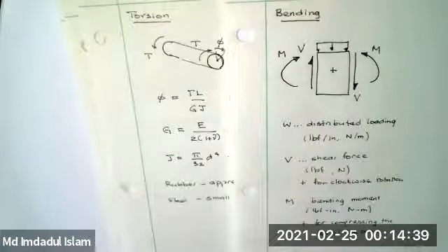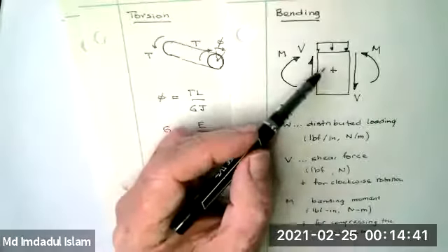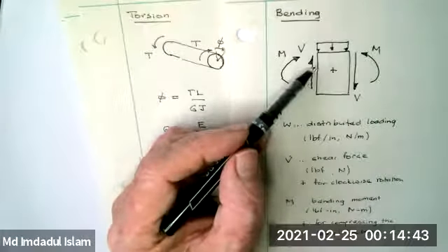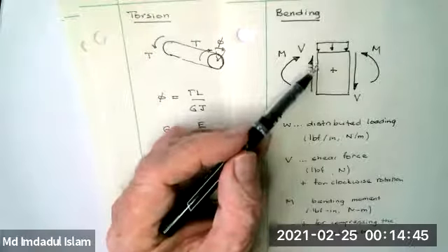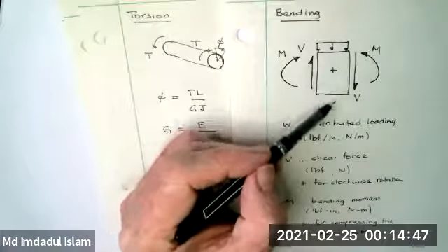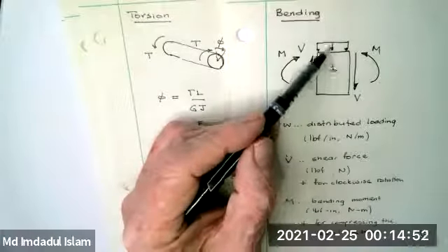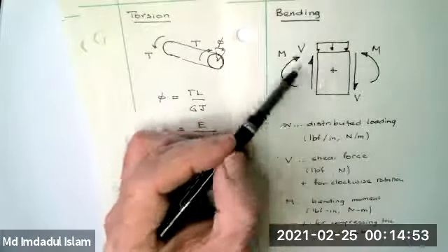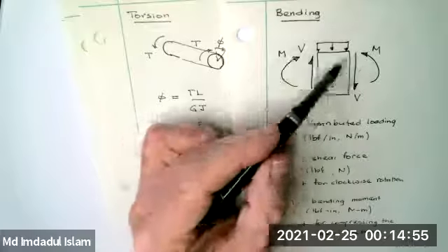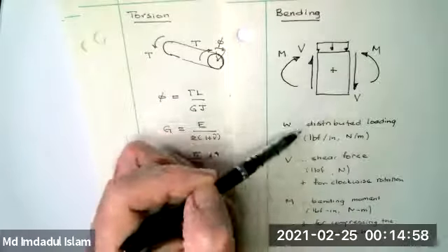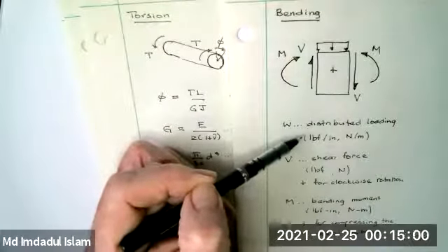This is a civil engineering convention because predominantly they design floors and like structures. The bending moment compresses the top and the bottom part goes into tension. The loads are typically down on things, and this is the bending moment they produce. So this is the natural sign once you pick this W. And this is the natural thing for civil engineering.